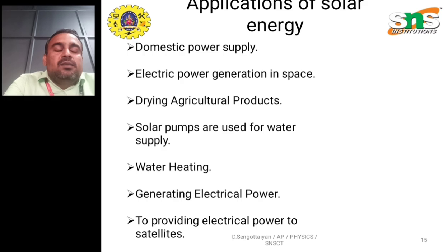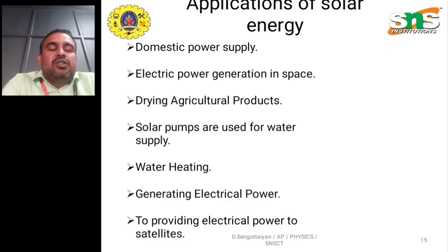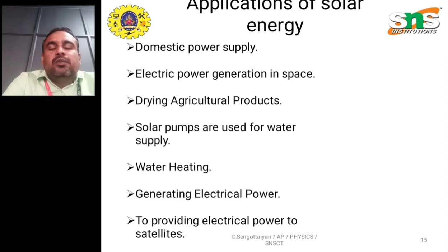In solar cells, mainly silicon type materials are used. Silicon type materials produce high efficiency, but the cost is very high. So in research we are trying to improve the efficiency and also reduce the cost of the solar panel or solar cells. Perovskite types of solar cells and dye-sensitized solar cells are currently being researched. Dye-sensitized solar cells produce less efficiency, but the cost is very low. Perovskite solar cells' efficiency is okay, but the lifetime is very poor. So we need to produce panels that require less amount of material, with high efficiency and a longer lifetime.